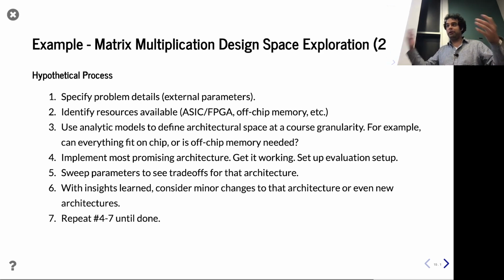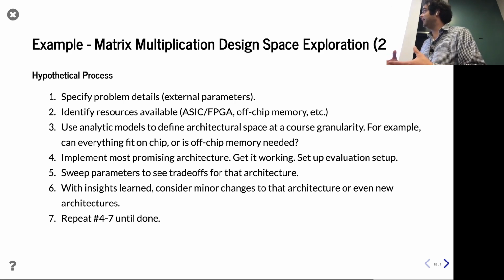And then based on that, you start thinking about plausible architectures. Okay, my design is going to be purely on chip. I can do this with SRAM. I have X millimeters squared of budget of area to build logic. Okay, well, perhaps I'll do this in a 1D architecture and try it out. So you say 1D maybe is your most promising architecture, implement that, get it working, get some numbers, get a